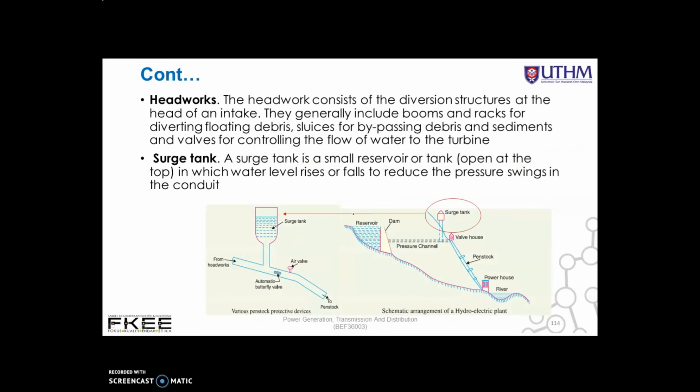And then headworks. Headworks consist of the diversion structures at the head of the intake. They generally include booms and racks for diverting floating debris, sluices for bypassing debris and sediments, and valves for controlling the flow of water to the turbine.